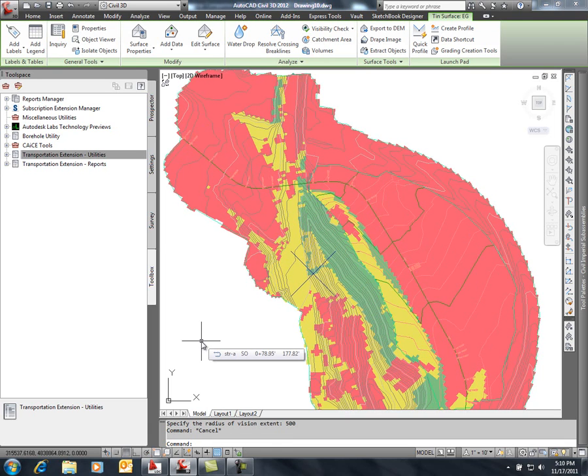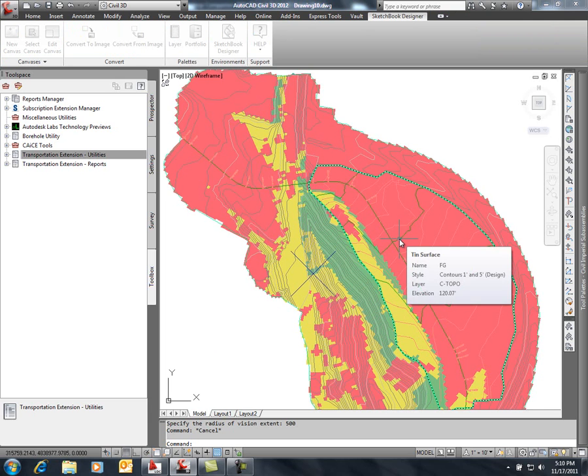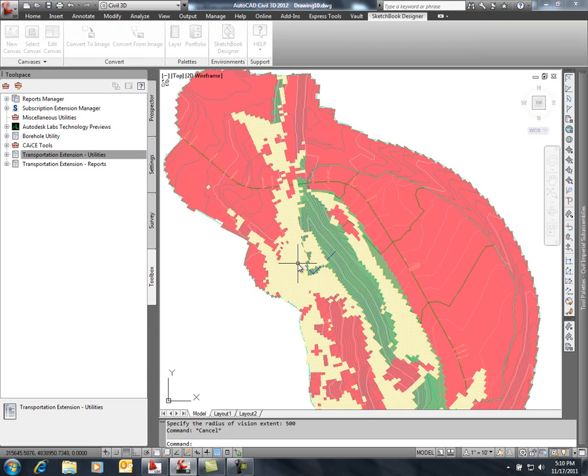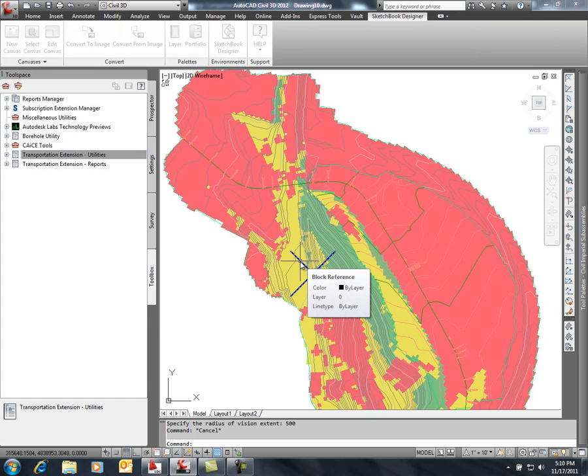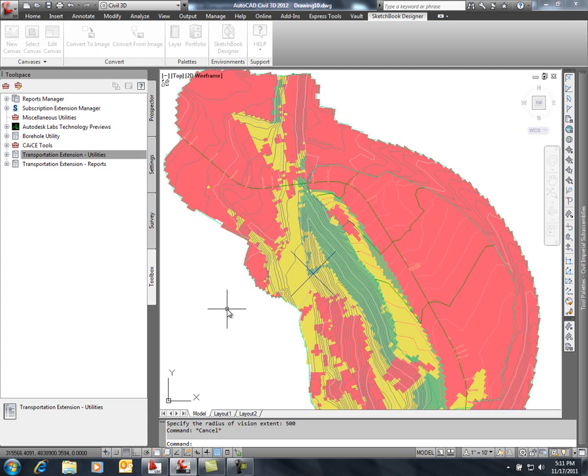All right. Now, keep in mind that these are elevations based on the surface, so there's not an eye height or something like that up on the road. It's actually a point on the ground. So one way that's easier for me to think about Zone of Visual Influence is to think about it more as what this can see. So if this is a 5-foot post, this 5-foot post can be seen completely from this area, but the 5-foot post, none of it can see any of the red area, and only some of the post can see some of the area that's marked here in yellow.